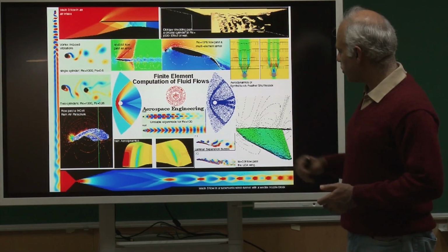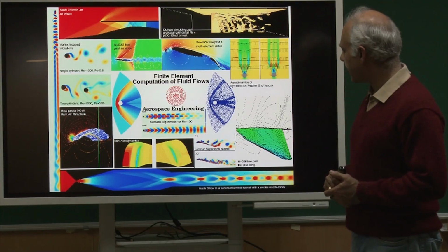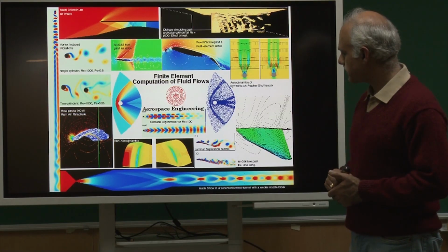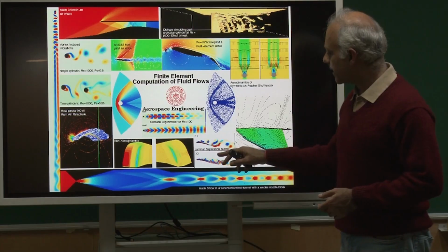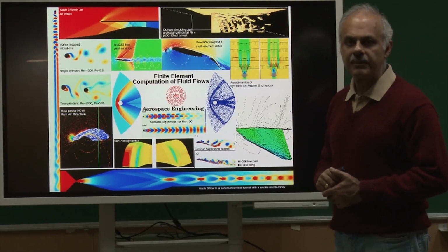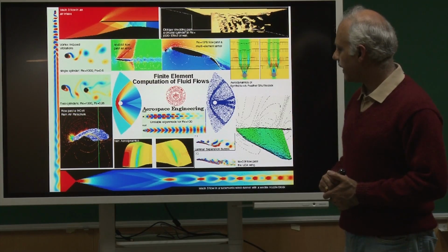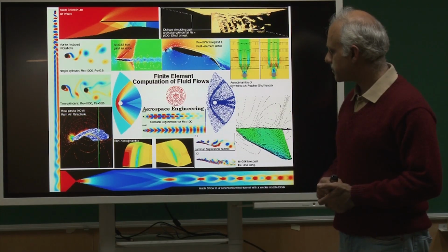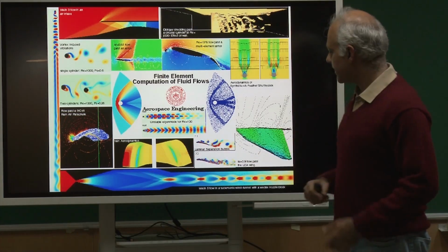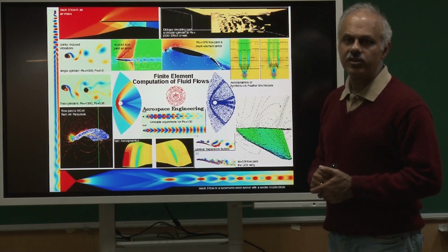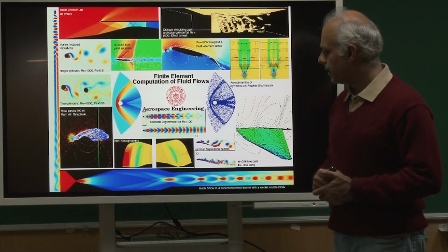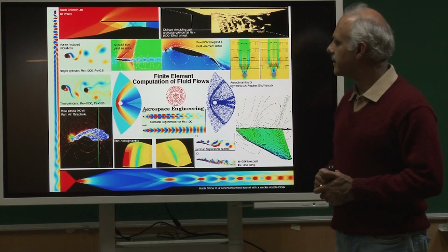This is actually a flow over a wing of an aircraft, a transonic flow. So, we were interested in looking at the shock boundary layer interaction. These are some studies to look at transition because of the laminar separation bubble on an Eppler airfoil, both in 2 dimensions and 3 dimensions. And this one is flow through a complete wind tunnel. So, if you want to design a supersonic wind tunnel, these simulations can help you with that.